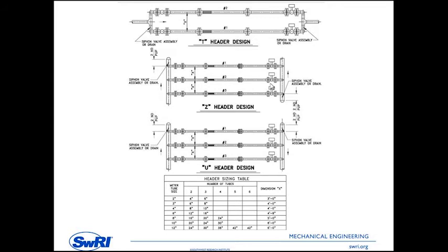In my experience, we always built a Z header because we knew we would have an imbalance, and we always made the run at the end of the inlet header the primary run on purpose because we knew it would max out first, and we were applying cascading tube switching such that this would be tube 1, tube 2, tube 3, and as we switched, we were always keying off of the flow rate on the previous run so that we would max out the entire station before we would overrange a meter tube.